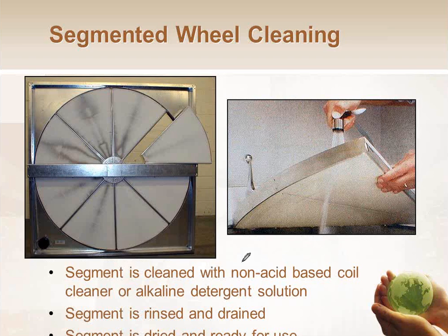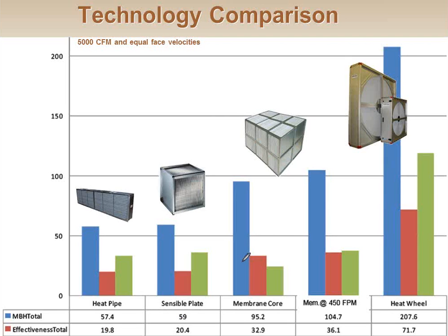If you decide to put them in a place that has things that are more polluted than other places, for example, a restaurant that allows smoking, or a bar or a casino with smoking, it is going to get dirty much faster, and that nicotine and tar is going to stick on there and reduce its heat transferability. So instead of cleaning them once a year, you'll probably end up cleaning them every couple months. But you've got so much air in a casino that the energy savings is probably worth doing the cleaning work. If you're in a state that doesn't allow smoking, then you're probably in good shape for most scenarios.